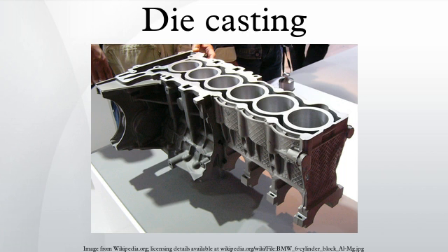Zinc: the easiest metal to cast. High ductility. High impact strength. Easily plated. Economical for small parts. Promotes long die life.